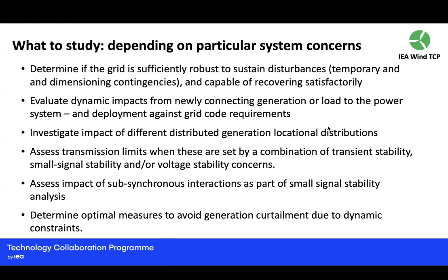Transmission limits. Historically, in these higher-level models you only look at thermal limits, but now stability constraints become more binding and they are below the thermal limits of transmission lines. What this means is that you can transfer more over a given transmission line, but because you have certain operational constraints on a cluster of generation, you cannot let them generate more, and that is translated into a transmission constraint.